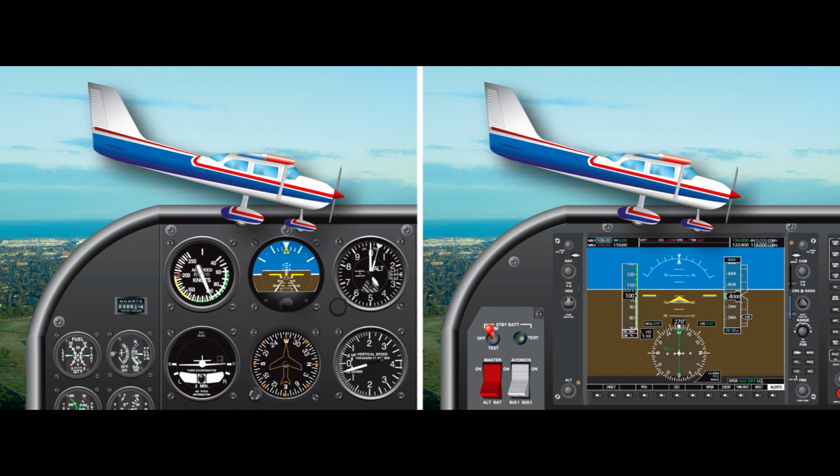Although glides are directly related to the practice of power-off accuracy landings, they have a specific operational purpose in normal landing approaches and forced landings after engine failure. Therefore, it is necessary that they be performed more subconsciously than other maneuvers because most of the time during their execution, the pilot will be giving full attention to details other than the mechanics of performing the maneuver. Since glides are usually performed relatively close to the ground, accuracy of their execution and the formation of proper technique and habits are of special importance.